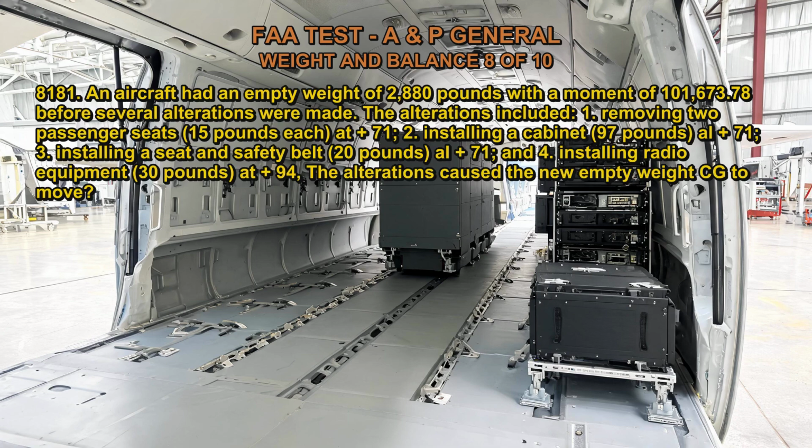Q8181. An aircraft had an empty weight of 2,880 pounds with a moment of 101,673.78 before several alterations were made. The alterations included 1. Removing 2 passenger seats, 15 pounds each, at plus 71. 2. Installing a cabinet, 97 pounds, at plus 71. 3. Installing a seat and safety belt, 20 pounds, at plus 71. And 4. Installing radio equipment, 30 pounds, at plus 94.